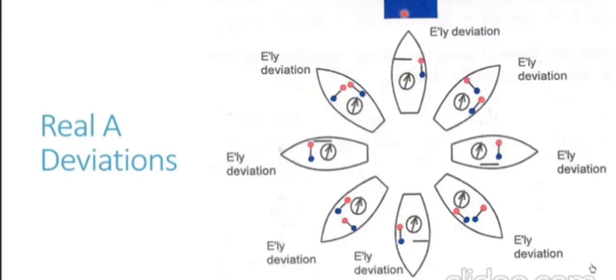Now with the magnetic field of the earth going vertically upwards, it will affect both these structures. It will affect the fore and aft longitudinal, and it is going to affect the athwartship beam also. The first thing to understand is that these are soft iron structures, so they do not have any permanent magnetism. But being soft iron structures, they can get induced by the magnetic field of the earth.